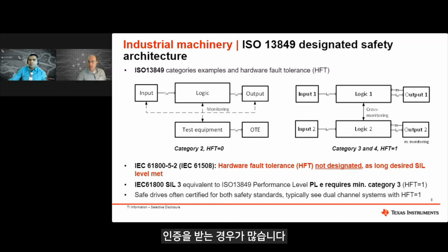To do the component FMEA, TI provides additional information for functional safety, such as for analog ICs, such as FIT rates for the TR 62380 and ISO 26262 Part 11, and also the Siemens norm. We also provide failure modes and failure mode distribution, as shown in Table 3.1 below.